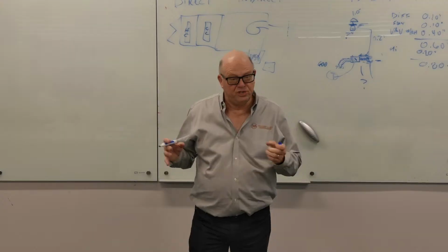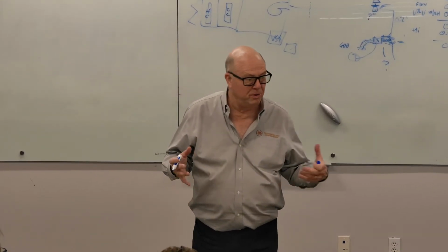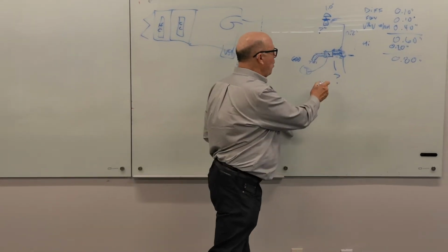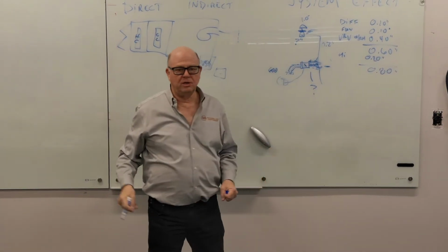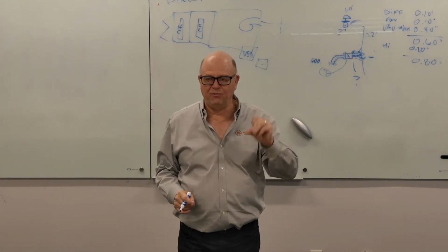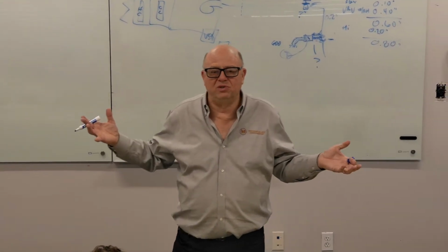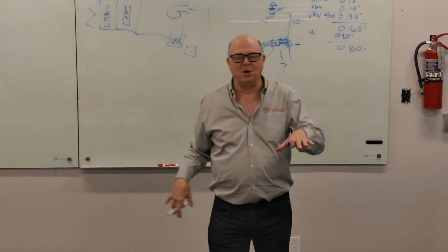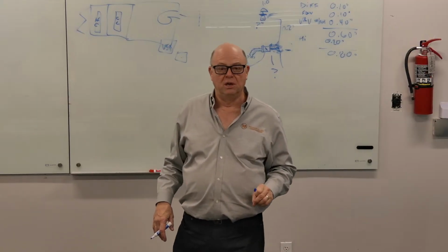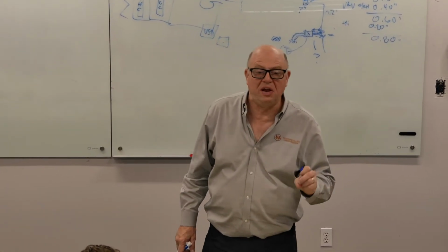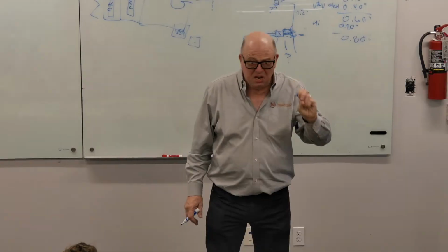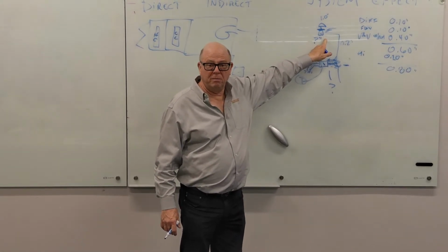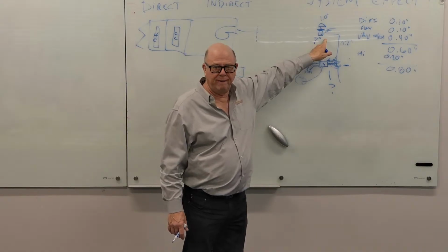But today, because we have super duper digital controls, we can do a global analysis of all the room set points and see how far off we are. Let's say all of them are set for 73. You know they won't all be the same, but you look at the differential. And if the warmest room is 73.5, so you're within 1/2 degree, well, maybe you can ratchet down that pressure because you are meeting the load, right?